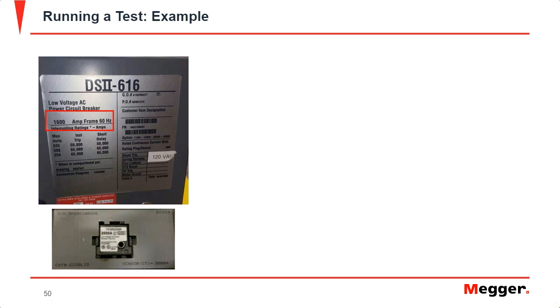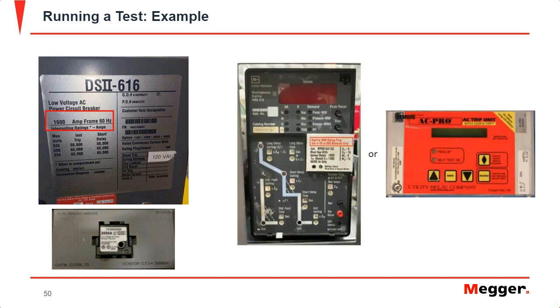Typically sensor plugs you'll see in your molded case breakers. So it wasn't derated or anything. We didn't have to worry about that. It was 1600 amp frame size. So we looked at the trip unit.